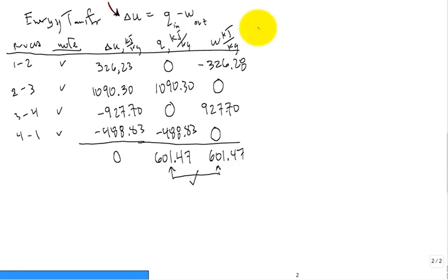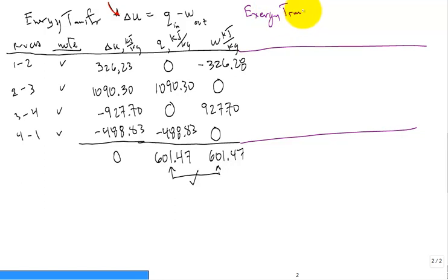Well, do this. Just go ahead and extend that table, and here, just instead of an energy transfer, think of exergy transfer. All right, well, what's going to be our exergy balance equation? Just like this was our energy balance equation, what is a good exergy balance equation? So you can have the change in the exergy, and I like to put a little extra x on that. The book doesn't, but I like to, so it's different than the specific energy, like you learned in chapter 2 in Thermo 1.